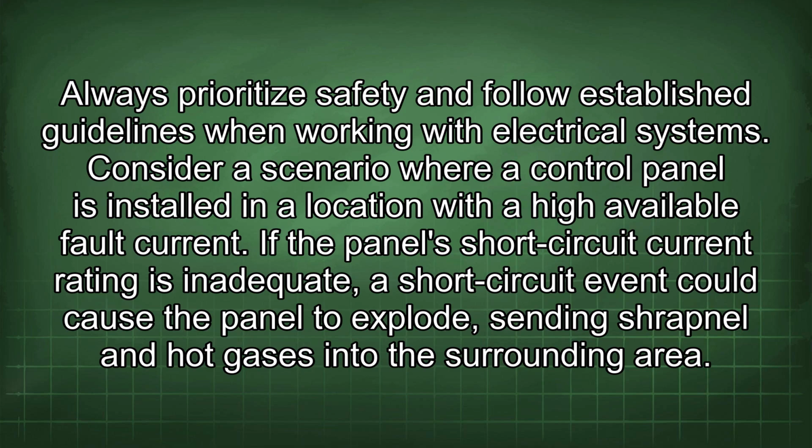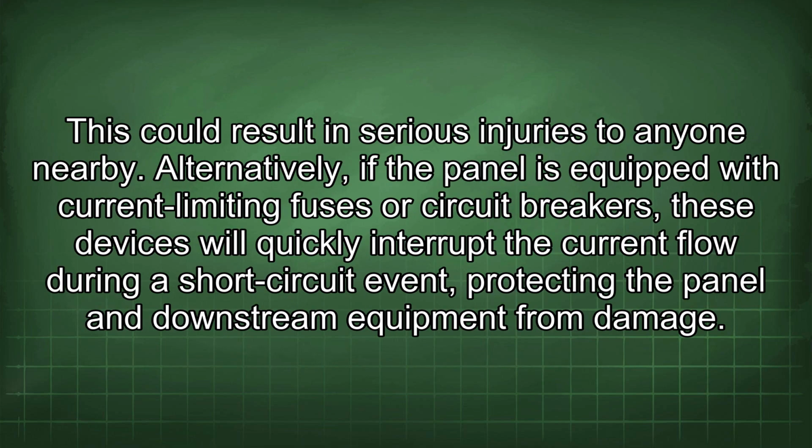Consider a scenario where a control panel is installed in a location with a high available fault current. If the panel's short-circuit current rating is inadequate, a short-circuit event could cause the panel to explode, sending shrapnel and hot gases into the surrounding area. This could result in serious injuries to anyone nearby.